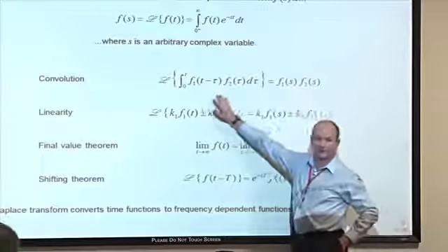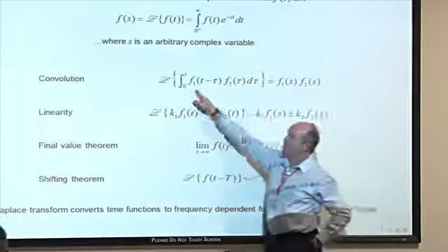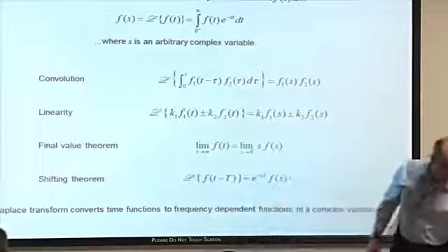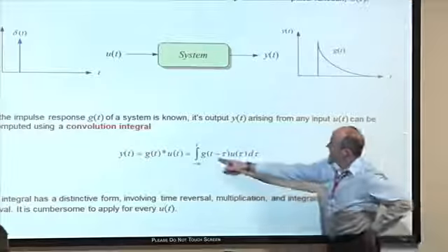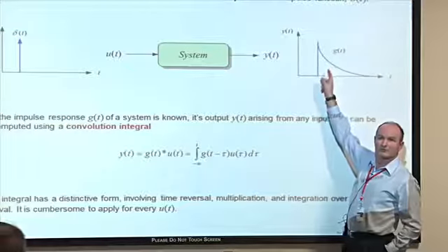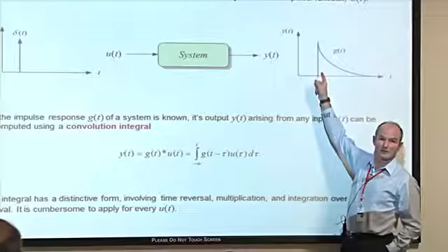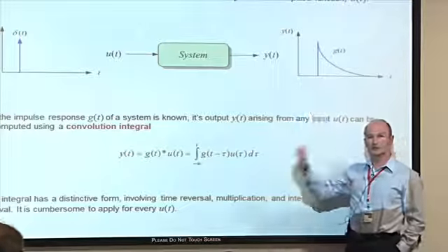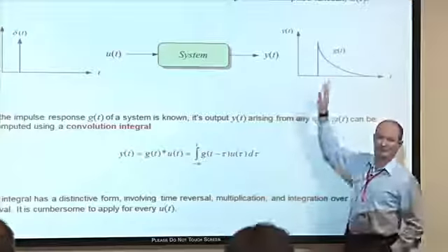We're replacing a convolution. Well, g of s would have been this function here, which, of course, in terms of convolution, is this function here. So if we take a Laplace transform of an impulse response, it's the transfer function that we get, and vice versa. Inverse Laplace transform a transfer function, you have its impulse response.